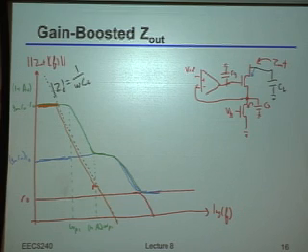Okay, so by the way, I'll explain in more detail in 1 second why this is a very important thing. I will say that even with this very small kink that I added here, this is actually somewhat probably exaggerated. But it's really important to know that this is there, because oftentimes this is small enough that even in SPICE, you wouldn't even be able to see it unless you really simulated right around those points, looked very, very carefully. But if you aren't aware of the fact that it's there, it can actually cause pretty big problems in terms of your overall circuit behavior. Okay? And the reason for that is the following. This kind of response here, where you have a pole and a 0 very closely spaced from each other, is what's known as a pole-0 doublet.